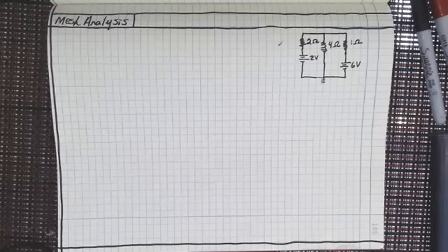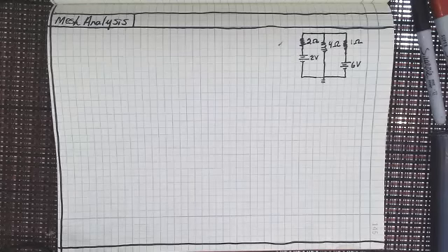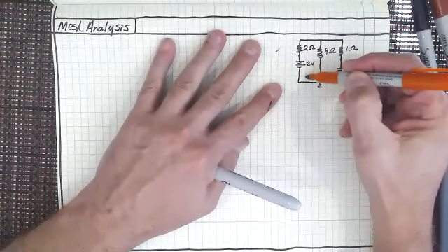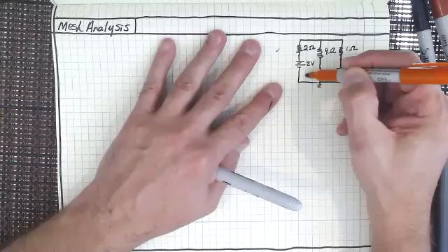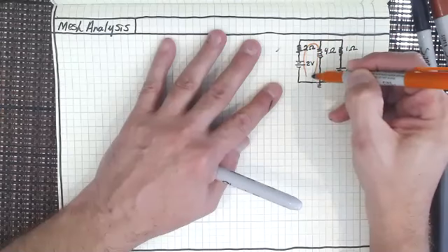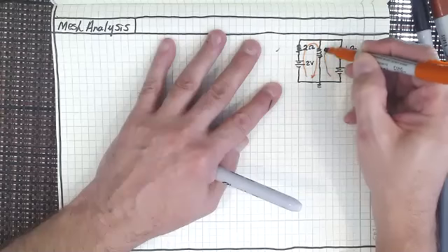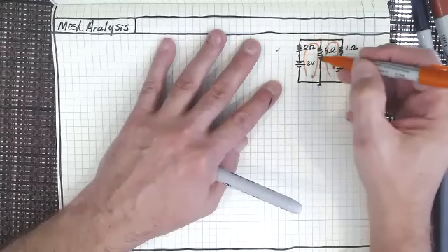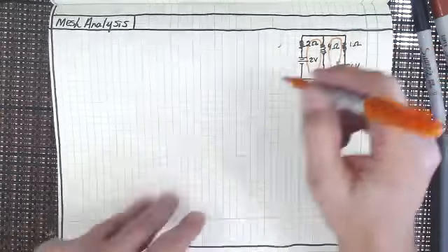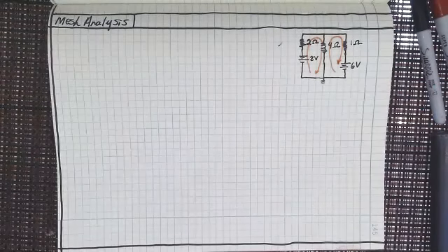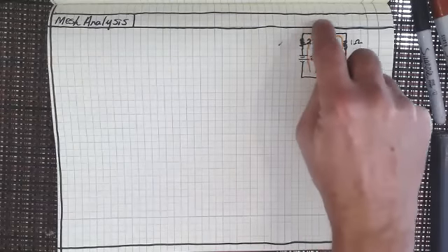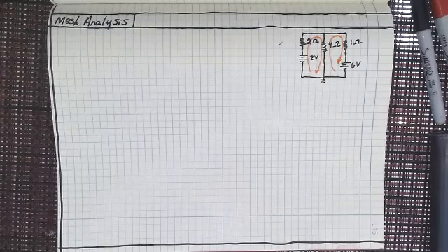And in your book, it goes through steps on mesh analysis and how you would do mesh analysis. But like I said before, the way that they do the summation as they work through a mesh analysis loop, I'm just drawing the mesh analysis loops right now, and you'll notice that they have to be in the same direction, right? So I've got all the loops going in the same direction as I sum the various different voltage increases and decreases as I go through that loop.